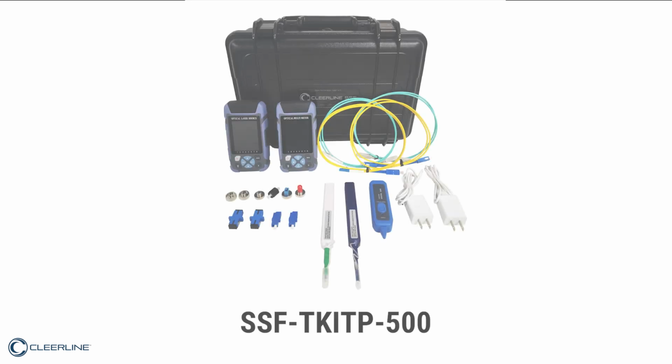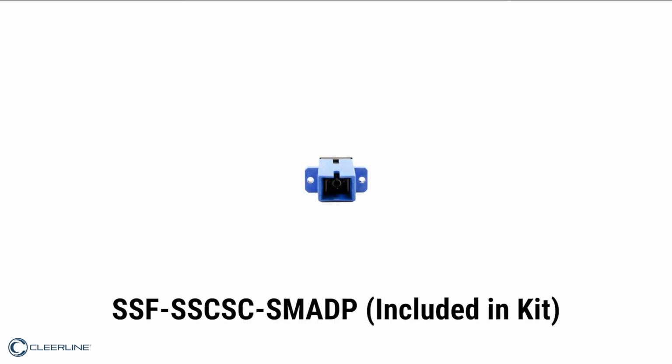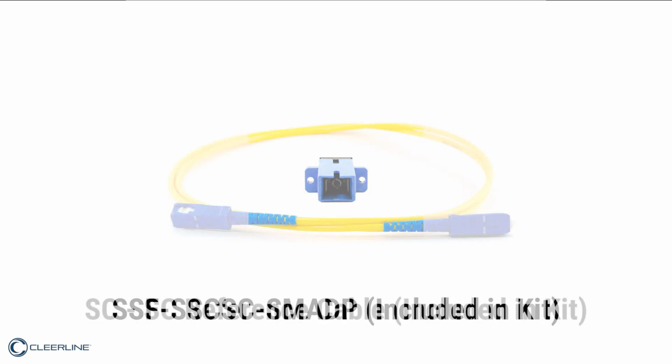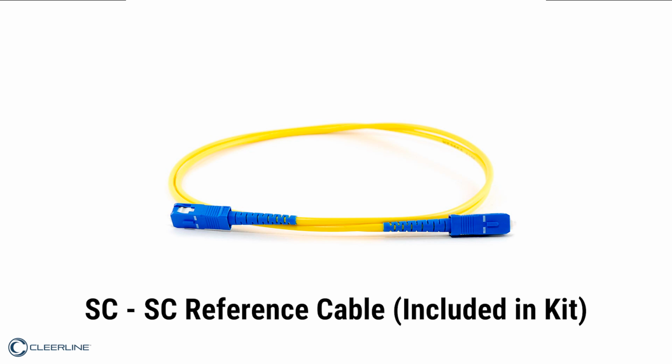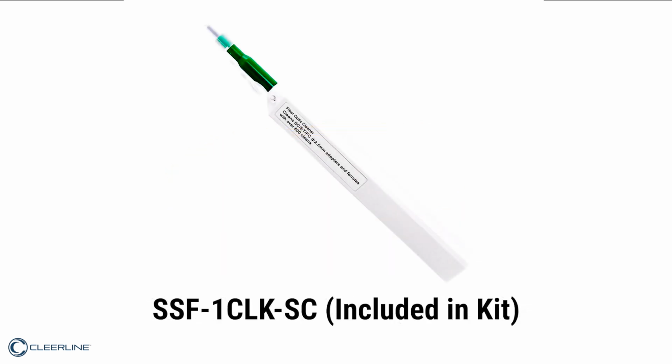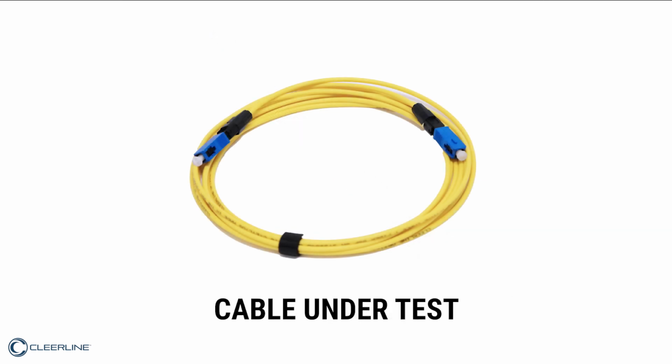Required equipment and materials for test: SSF-TKITP-500 with included reference cables, adapters, and cleaning supplies, SC to SC feed-through adapters, SC to SC reference cable, SC one-click cleaning tool, and cable under test.